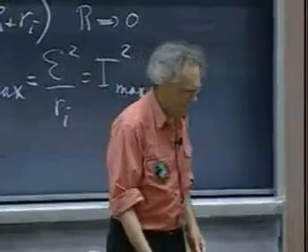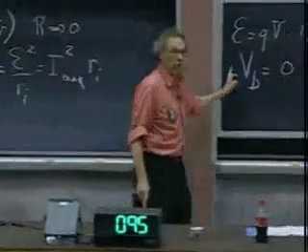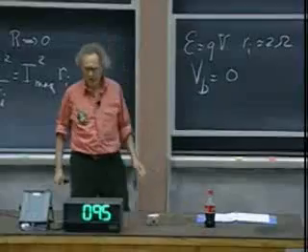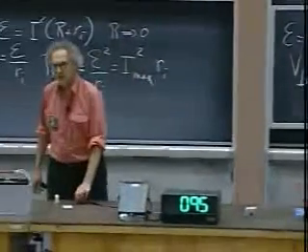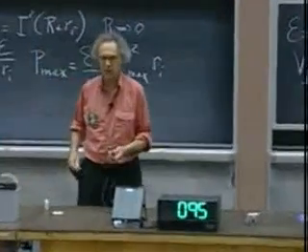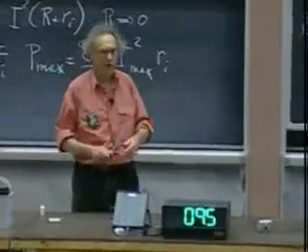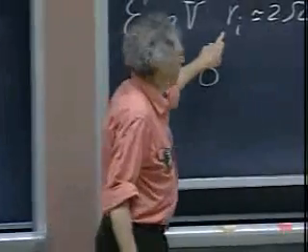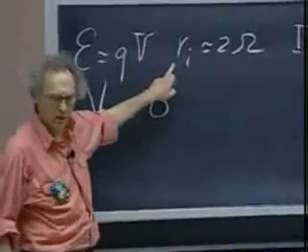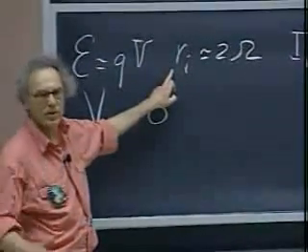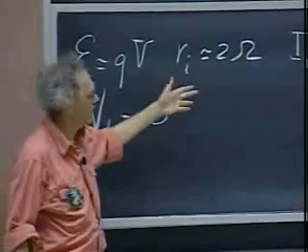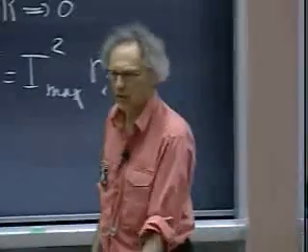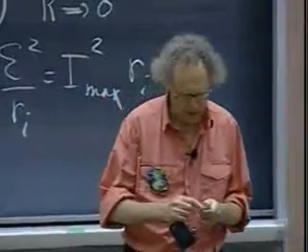And so the voltage that you're going to see is going to maybe not go to 0 exactly, because my key may not have 0 resistance, but it goes very low. And what you cannot experience is something that I can, that this battery will get hot. This 40 watts will be generated inside here. It is possible, though, that when the battery gets hot, the internal resistance may even go up a little, because remember that resistance goes up when temperature goes up, in which case the power will go down, so it may not be the full 40 watts. But I can assure you that I can feel this thing getting warm. So let me short it out now.